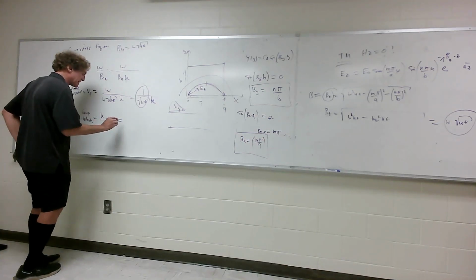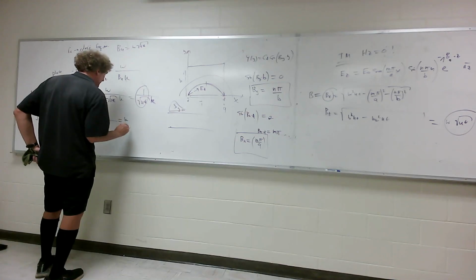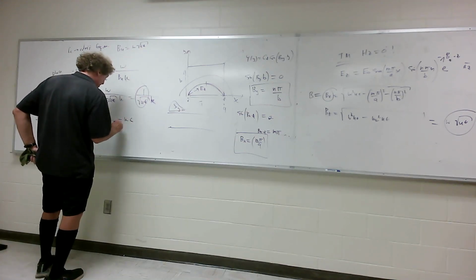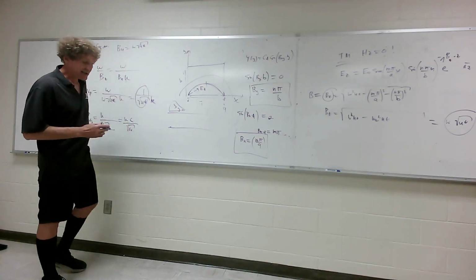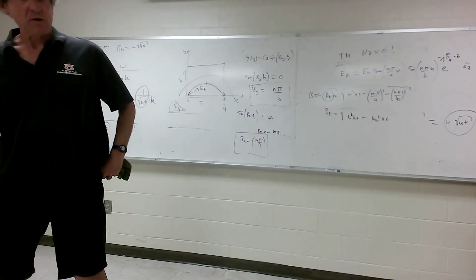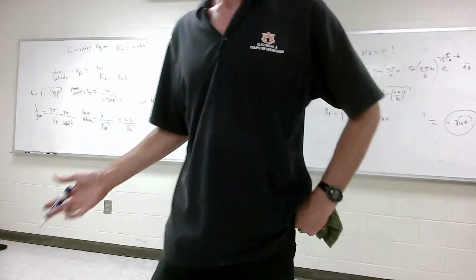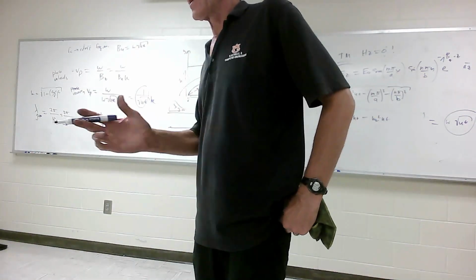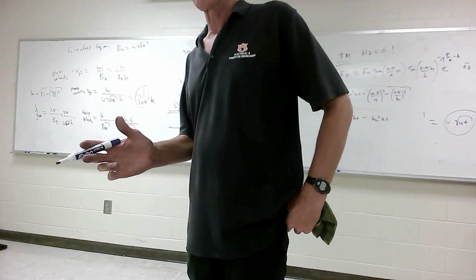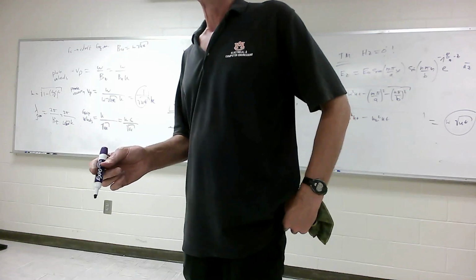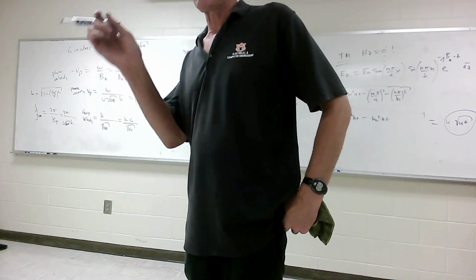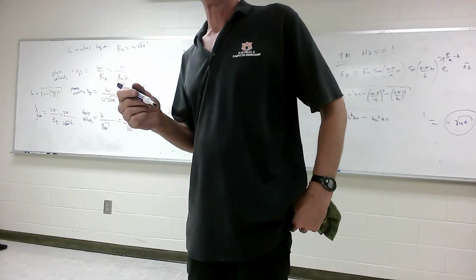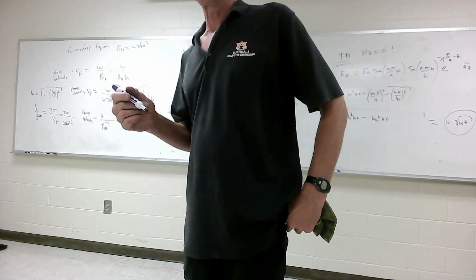And here it becomes k times c over the square root of epsilon relative. Now remember, the largest value k can have is 1. And as you get closer and closer to cutoff, for lower and lower frequencies, it goes to 0. So the actual rate that energy propagates will go to 0 at cutoff. Y'all with me on this?